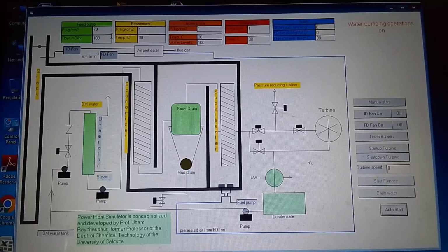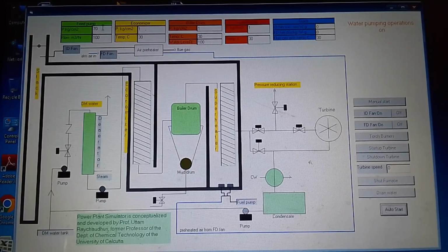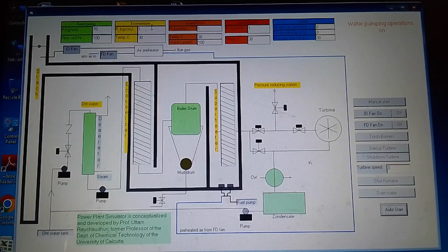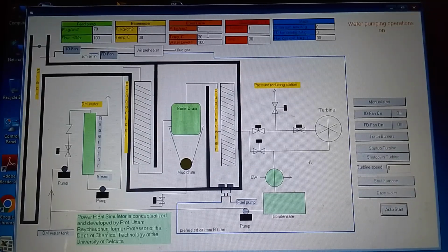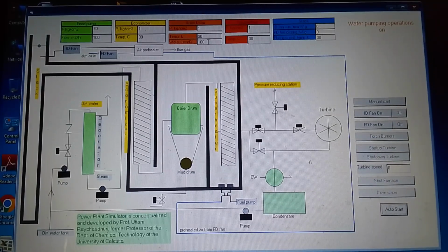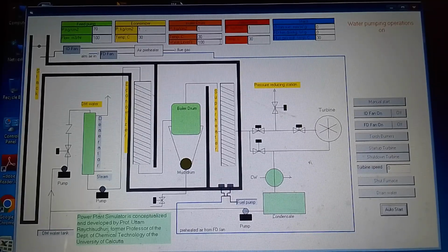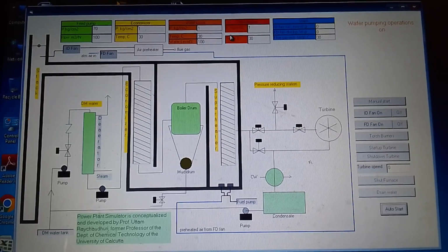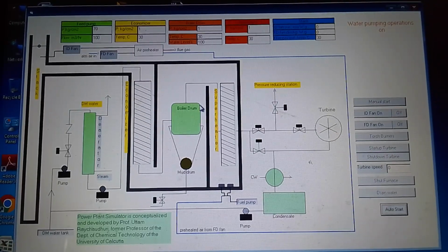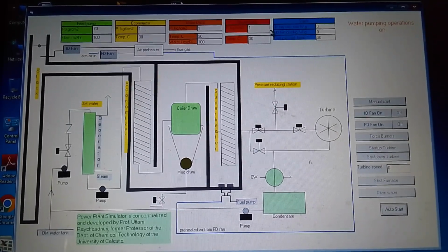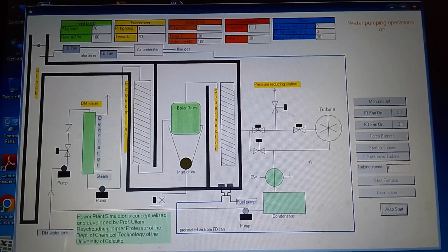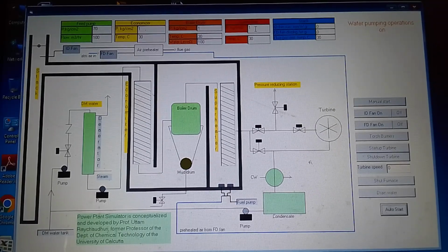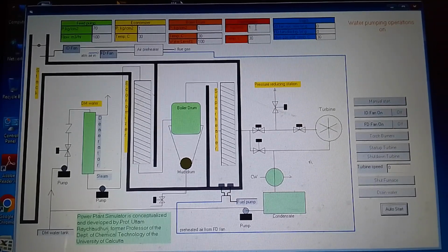At the top you will see the control panel which shows the feed pump pressure and the flow rate, followed by the economizer tubes where pressure and temperature of water or steam is given, and the boiler drum, where the saturated pressure and temperature are shown, and the level of the drum is also controlled. You will see a level of 50 or 40% maintained in order to avoid steam leakage down the mud drum. And then the superheater, where the temperature is more than 400 degrees centigrade, and pressure is 65 to 70 kg per centimeter square.